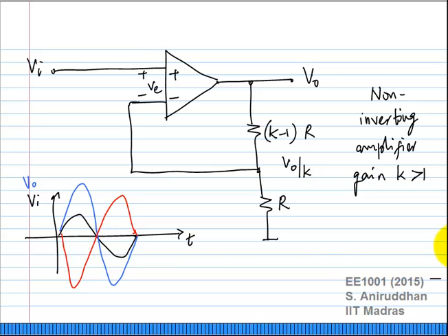As long as it looks like some kind of integrator, that will happen. You will see in later courses why. If you want to apply a sinusoid here, then the value of omega u matters. In this course, we will assume that omega u is very large anyways. Even if you apply a sinusoid, you can assume that the gain of the op amp is very large.